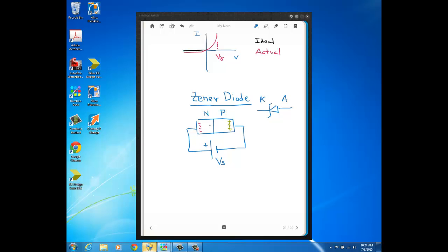Well, if you look at what happens with the free charges when you have a reverse bias case, ideally all your free electrons on the inside migrate over to the far end of the N region, and all the positive charges migrate to the far end of that P region, because these positive charges are attracted to the excess electrons that are on the negative terminal of the battery, and these free electrons are attracted to the excess positive charge that's on the positive side of the battery.